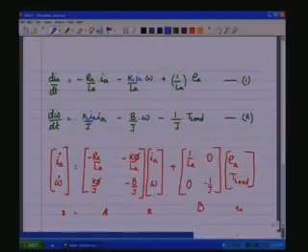So, we do not, because there is no state multiplication, I A into omega, I A into I A, this is I A square, this is a non-linear system. Therefore, we do not put it in the standard matrix form, we just leave it as a differential equation system. So, that would become a non-linear system, but still that would give you the entire dynamic model of the DC